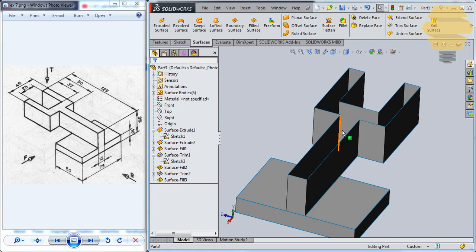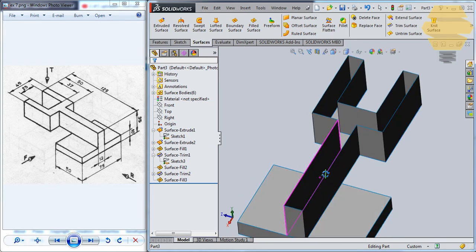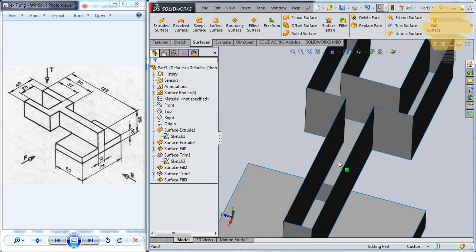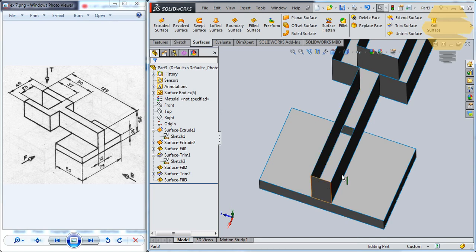So you need to do surface modeling in such a way that there is no surface that is extra. Once I fill this surface also, this can be considered almost like the solid model without any extra surfaces in between. By saying that, what I mean is, if I hadn't removed the surface, then this would not be a continuous surface.